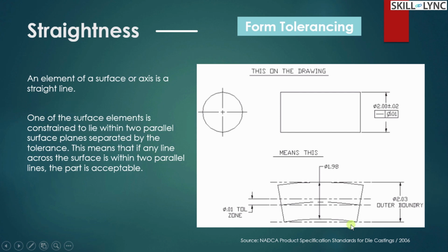So this is how you can see the symbol is going to add on. The tolerance zone will control the shape, the form of this object. You can slightly go through this again. This tolerance is going to be the overall size tolerance that is permitted, that is the straight line drawn to here. So this is the allowed variation of that object, but considering the two datum planes, the straightness can be measured with the datum reference plane for this element. So for that the total dimension can vary. For this point the tolerance is acted upon, and hence it is 2.02 mm.